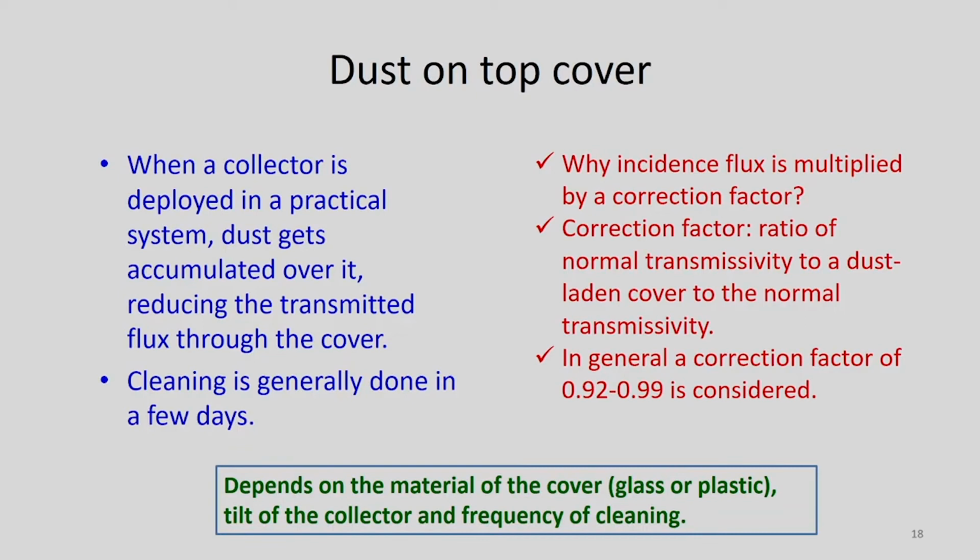When the collector is deployed in a practical system, dust gets accumulated over it, and that reduces the transmissivity of the glass cover. That is why it is recommended that the glass cover or PV system be cleaned from time to time. Of course, it is recommended to clean daily, but that is not possible, so cleaning is generally done in a few days.